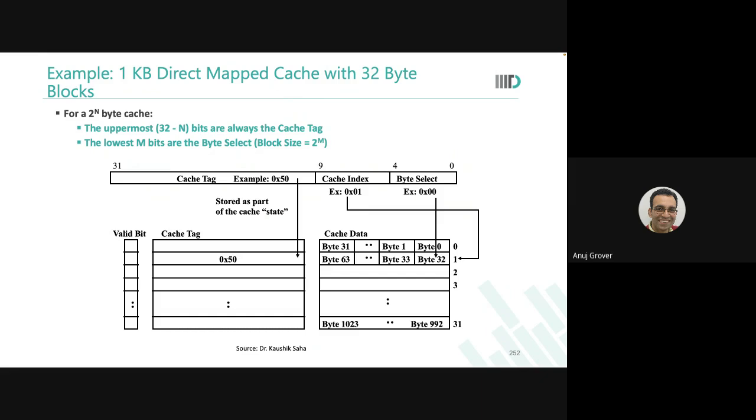Not a strobe signal. A strobe signal just comes and goes. This is an address. I need the 5th byte of that particular line to be sent to me. Strobe is also a multi-bit signal. So what I understand, probably there is a language mismatch here. What I understand with the strobe is you give a small strobe and say that, okay, I need new data.